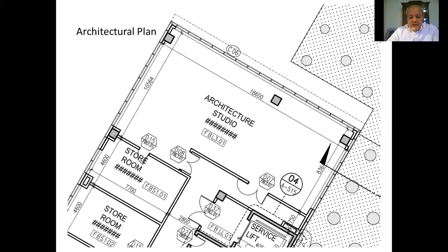This is, instead of looking down from the level of 1.5 meters to the plan, like what we see in front of us, no, instead we look up. But we start with developing the architectural plan. So the first stage is that we start to indicate the location of the center lines, the location of the structural systems, columns, shear walls, everything that is structural. We have to indicate it.